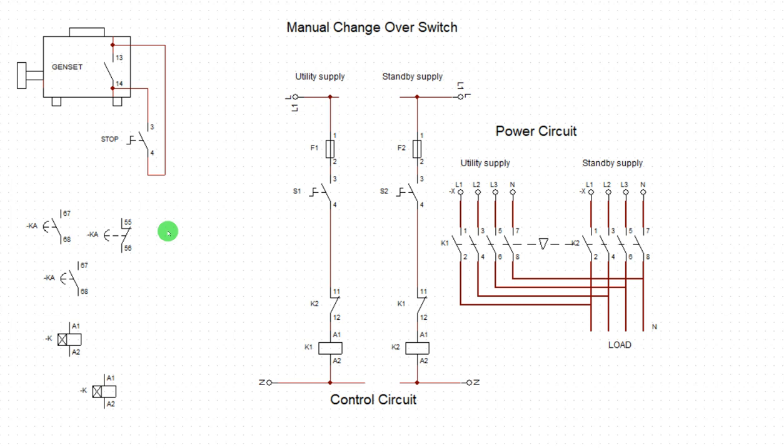Let me repeat again. When the mains come active, I don't want the mains to go in immediately. I want the voltage to stabilize, because sometimes the voltage might come with high voltage, then people will start putting on load, then the voltage will now stabilize. So I want that transition time. I want a few seconds. When this one comes active, I don't want it to take over immediately. I want it to hold on for a few seconds, and that few seconds is to enable the voltage to stabilize. After that few seconds, you should knock off this and take over.